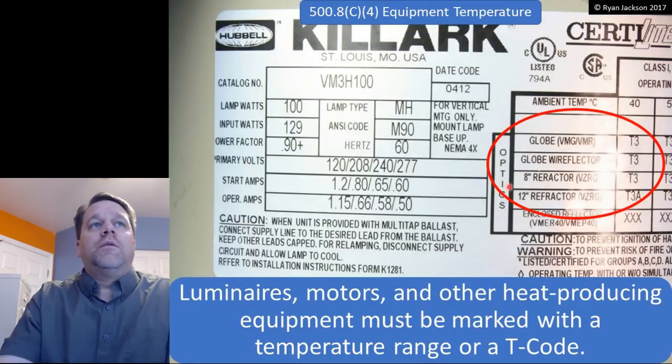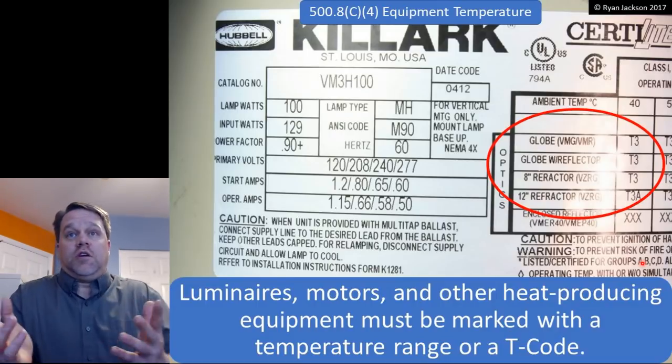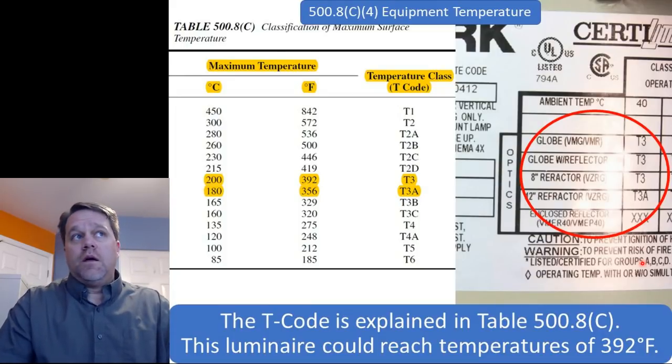T3, that's the globe. T3 if I have an 8-inch refractor, but if I have a 12-inch refractor on this luminaire, it's actually a T-code T3A. Okay, so what does that mean? Fine, it has a T-code, great. Well, what do I do with that information? Well, if I go to table 500.8c, I can look at what the T-code means.